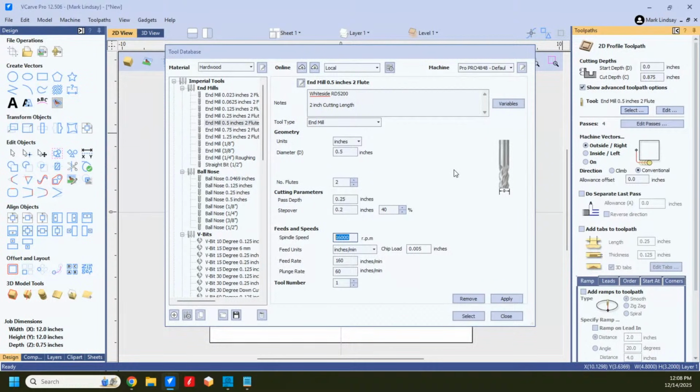I'm talking X-Carve. I'm talking Shapeoko. And not the current edition, but the earlier edition. Some of you have some of the smaller hobby machines. Now, it may be possible, in fact, I know it's possible because I've done it, for me to use this 1/2 inch bit and cut through 1 inch thick material in one pass. It's easy for me to run this bit with this kind of a pass depth. It's easy for me to run this at double this speed. Yes, I've run it at 320 inches per minute, cutting 1/4 inch deep. I've done it.